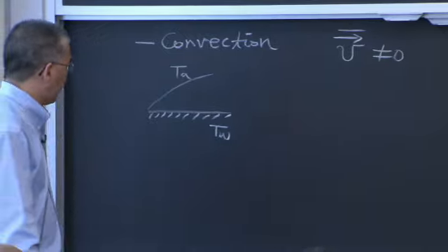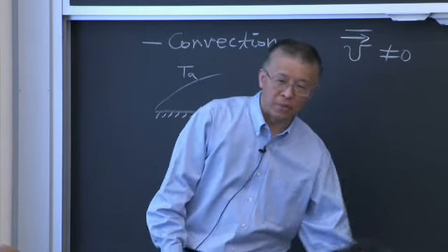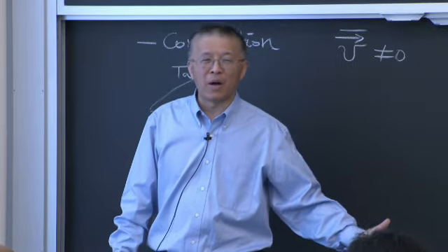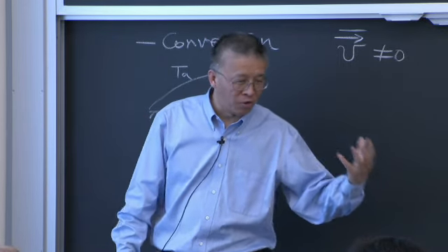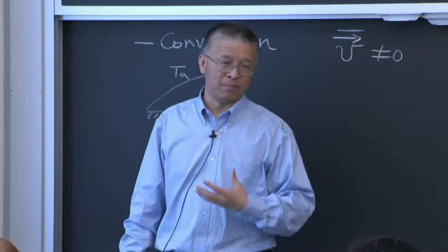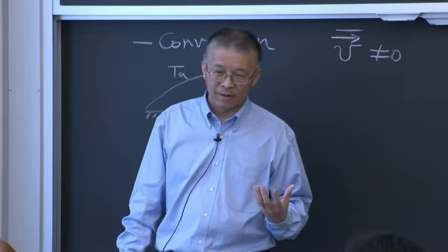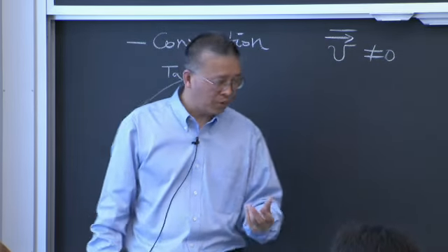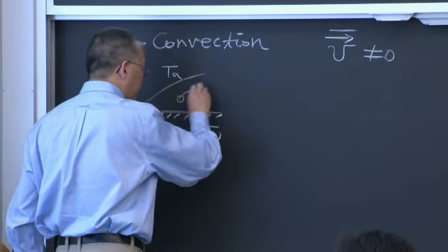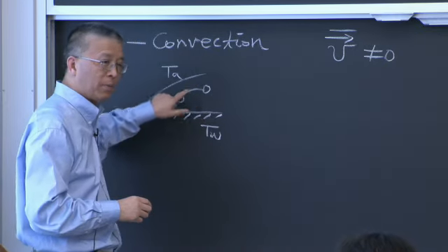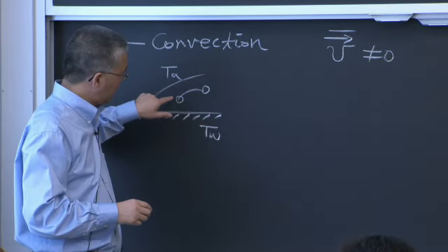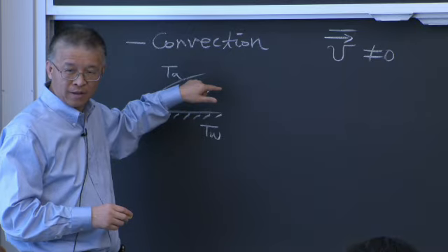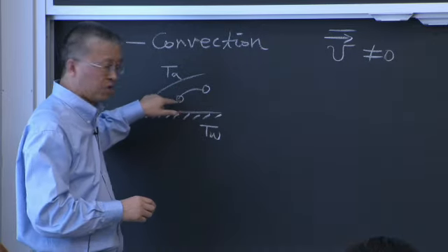That could be 1 meter per second, 2 meters per second. Molecules are always doing random motion at 300 meters per second, much faster, but convection is more effective. That's because it's not diffusion: when they move from one place to another, they carry all that energy directly from one place to another. That energy is enthalpy.